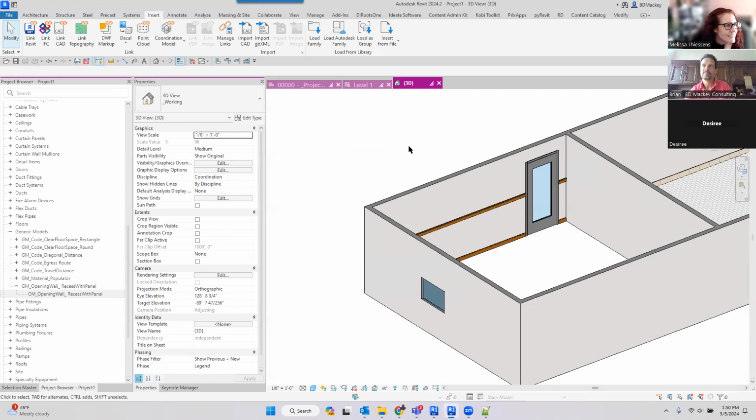All right. Let's see. Tim's asking, what are the best practices for working in a work shared model with multiple users with design options? Users are asked to relinquish frequently. It seems that has been reported in the Ideas Forum, but Autodesk has not addressed this yet. Yeah, unfortunately, the way that works is when you check out a design option, it's similar to a group. You take ownership of that design option and everything inside of it. So if you go edit a design option, you now own that design option and every single thing inside of it. So only one user at a time can work in it. That's just the limitation. That's the world we live in.